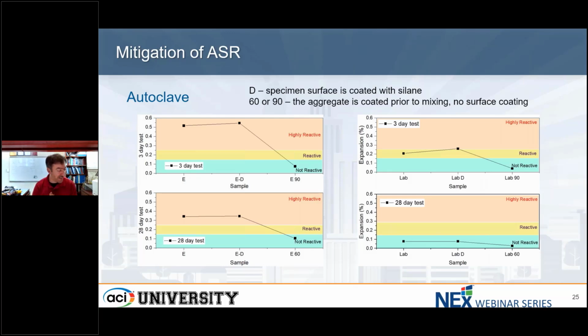And it's my, again, personal opinion that we are actually causing expansion due to cracking in some cases due to the thermal shock rather than actually measuring ASR expansion. Waiting to 28 days to do the same test, the concrete is a lot more resilient to that thermal behavior, and I think we get a better reading. Now, if we're thinking military applications, yeah, they're not going to wait 28 days to go build something out in another country trying to figure out if the sand is reactive, so maybe that's not the best recommendation. But for DOT work, where we usually have months to do stuff, it's maybe a little more plausible.